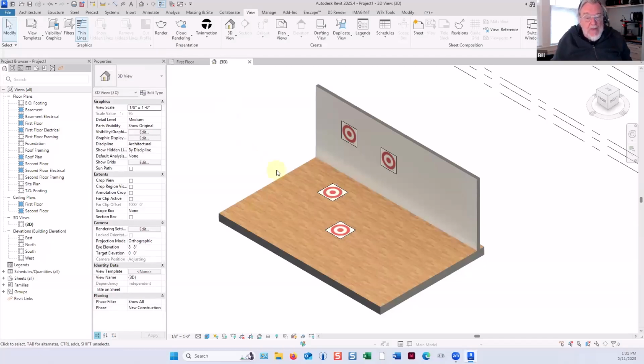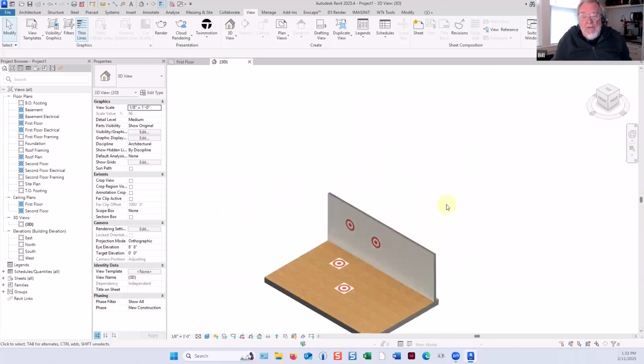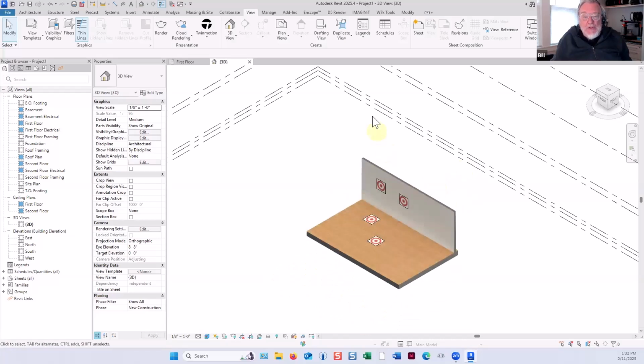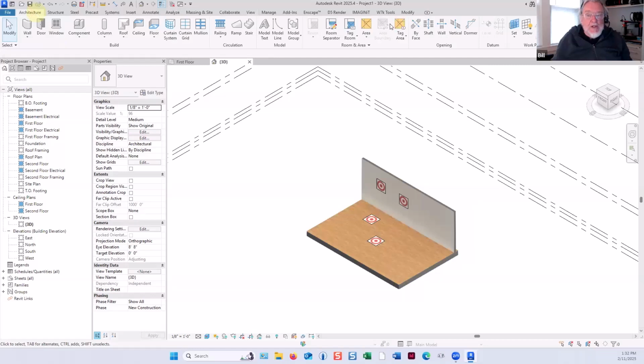Okay, let's look at what we can apply them to. I'm going to create a cylinder here. If you remember, the active work plane for this view is down here on the footings. It's crazy. So I'll make this my active plane, so I can draw things in 3D on that floor and not actually be on that floor. So I'm going to go to architecture, set the work plane to the top of the floor. So now when I draw things, they'll be there.